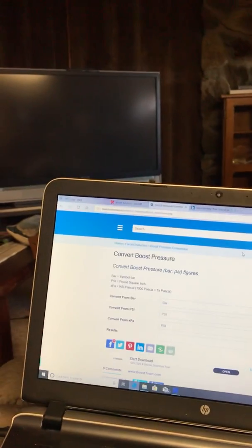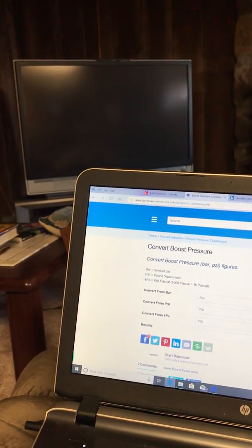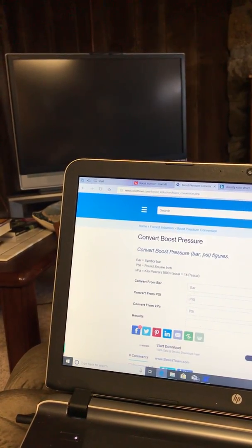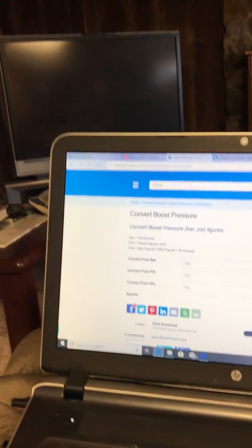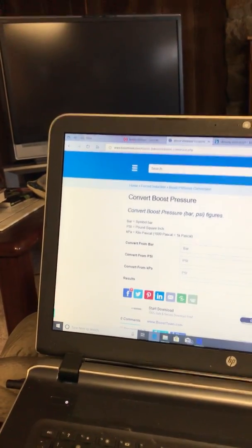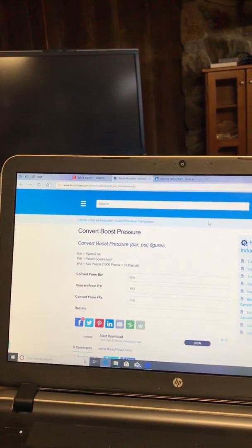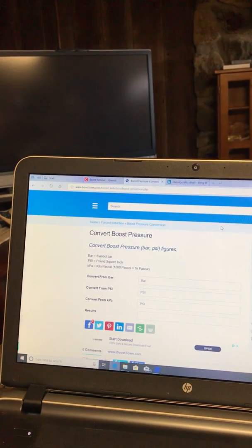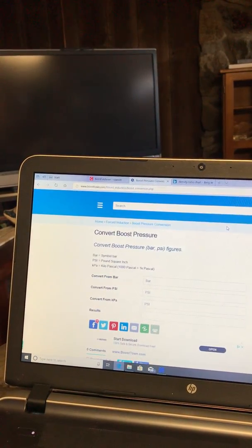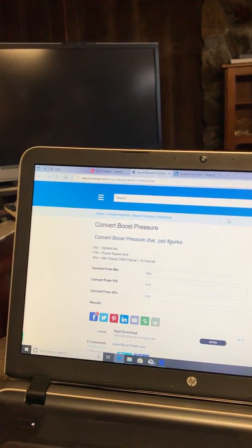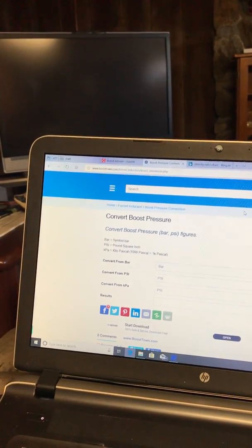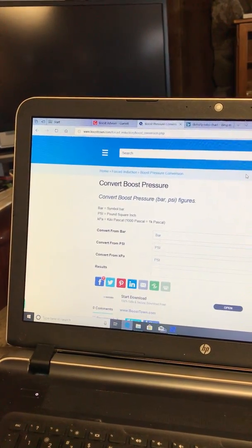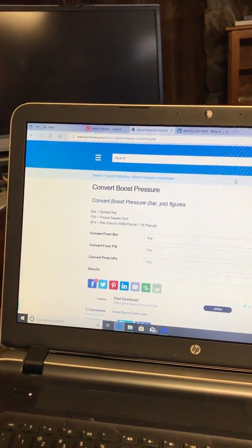First video we were looking at 800 horsepower at 3,000 RPMs from a typical 5.9 Cummins, and I left out a few things from the video that I'm going to address this time. One of them is I gave some numbers that we needed for the turbo to perform to. It was, I don't know, 80 some pounds a minute at I think it was 4.6 pressure ratio, and I just went right to the compressor maps with those numbers, and I never told how I came up with those numbers.